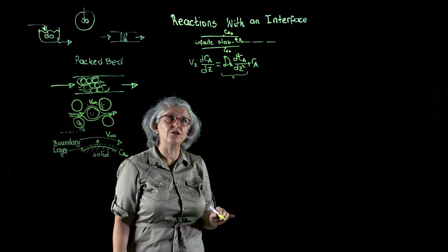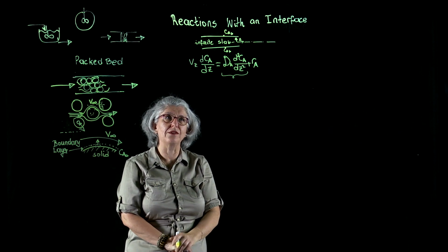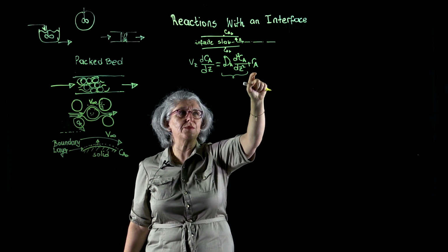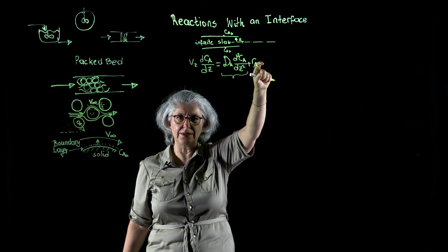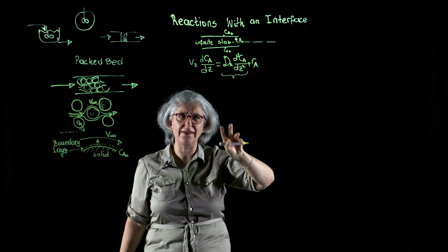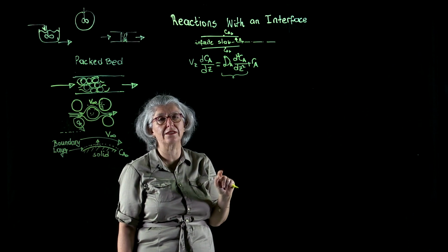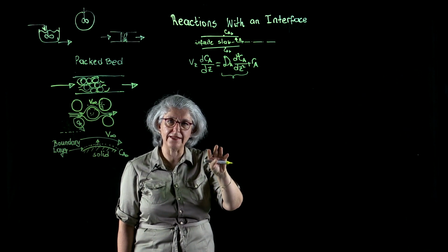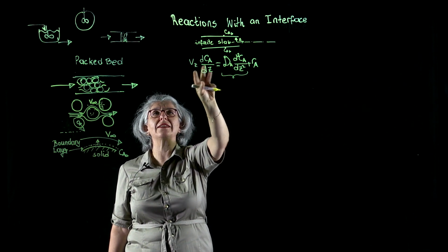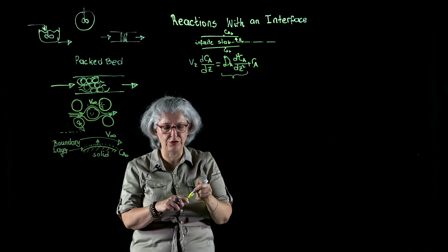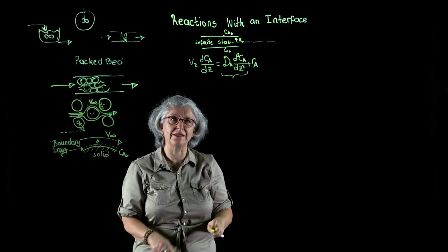So, one more time, if our reaction is slow, our rate expression appears in the balance equation. If our reaction is very fast, our rate is going to appear at the boundary condition. That would be the condition representing heterogeneity. Now, let us say that our reaction rate and the rate of diffusion are comparable, as well as the advective flow. All right? So those three components are present in our balances, and we're going to have some boundary conditions.